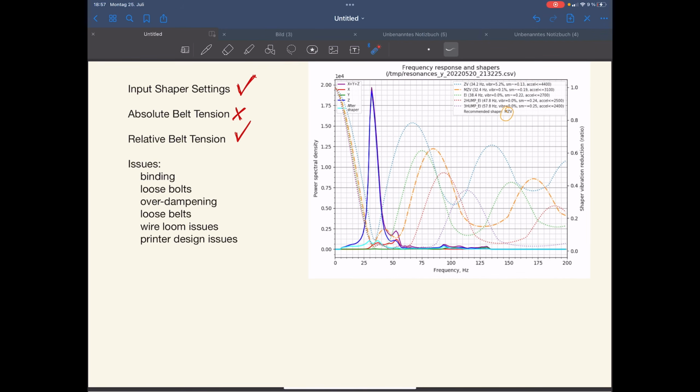So the last thing we are going to have a look at are recommended accelerations. And this is something which is quite controversial, but in my opinion, it is not a good way to follow those rules. Like if you are printing and it recommends you to stay below 4,400 millimeters per second squared, and you just set this as a limit. You have to look at what you are printing. If we are, for example, looking at the benchmark itself, the Benchy will be looking really nice at 10K as well.